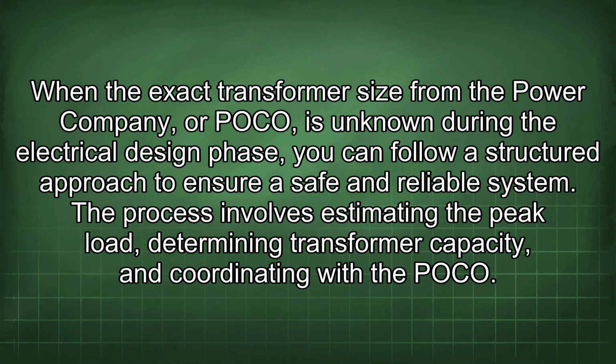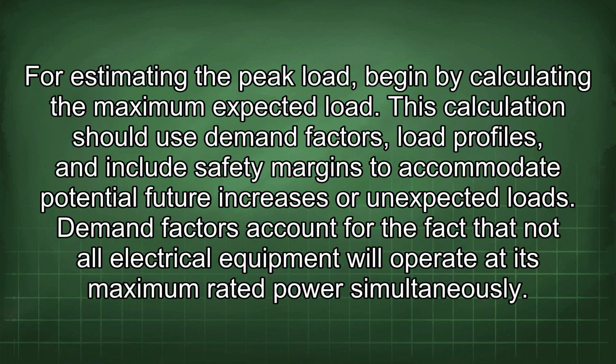When the exact transformer size from a power company, or POCO, is unknown during the electrical design phase, you can follow a structured approach to ensure a safe and reliable system. The process involves estimating the peak load, determining transformer capacity, and coordinating with the POCO. For estimating the peak load, begin by calculating the maximum expected load.